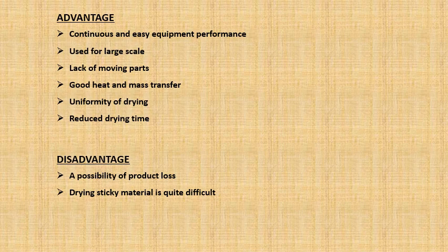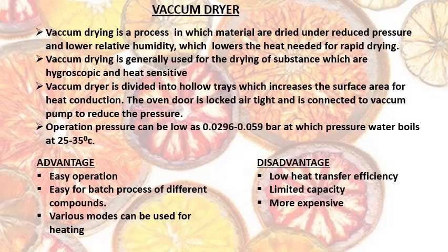And next, when we're talking about its advantages and disadvantages. Advantages: continuous and easy equipment performance, used for large scale, lack of moving parts, good heat and mass transfer, uniformity of drying, reduced drying time. Disadvantages: a possibility of product loss, drying sticky material is quite difficult.